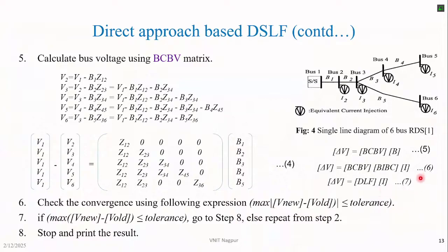So from this analysis, if we observe, every time we update our branch current or voltage, the impedance is not going to change over there. Impedance remains the same. The only change you will obtain is that your bus voltage keeps on changing.